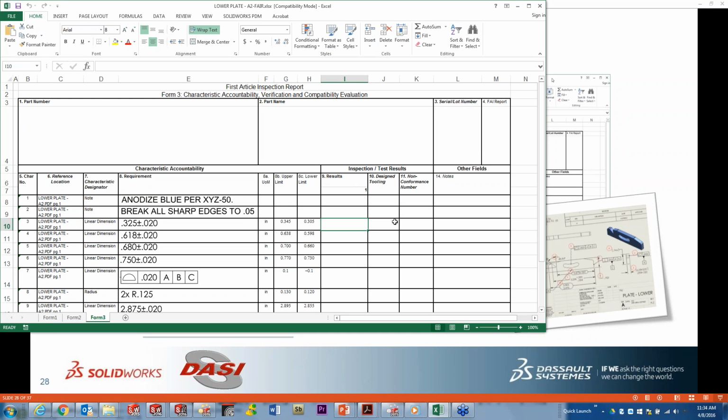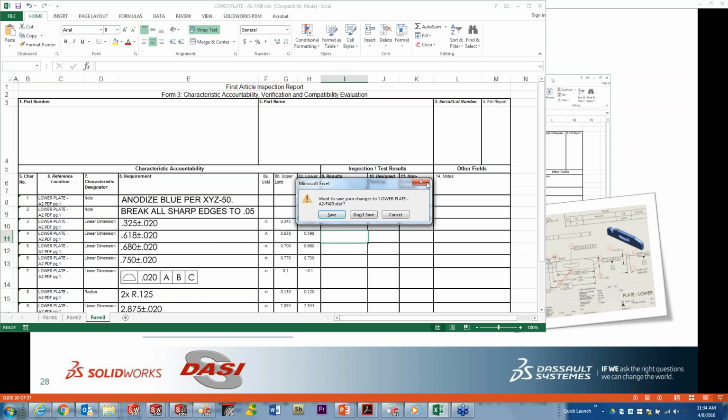Using this tool in a manual method, if I see that I have a 0.325 tolerance with a plus or minus 0.02 on that, if I type in, say, 0.315, well, that makes that dimension right down the middle. And using different templates can have different types of data validation to show you color feedback for each of those. I'll do that in the next one.